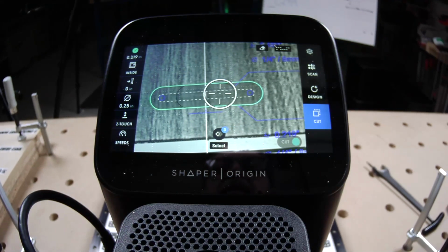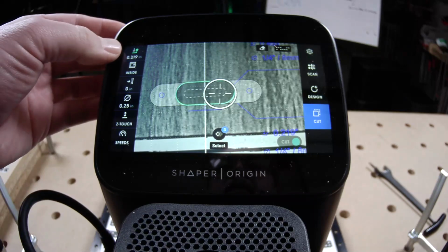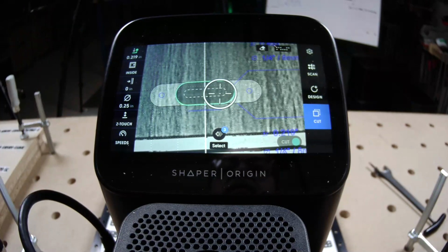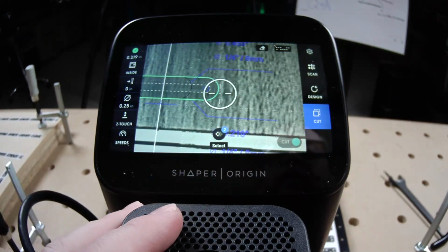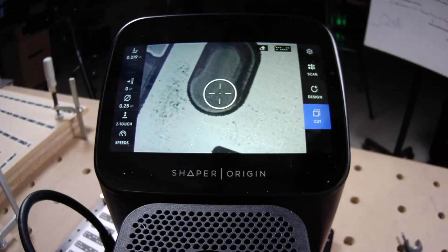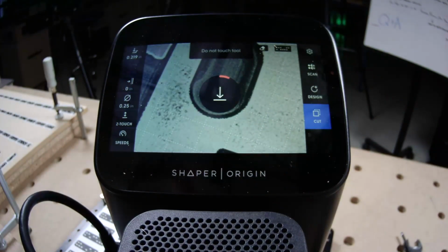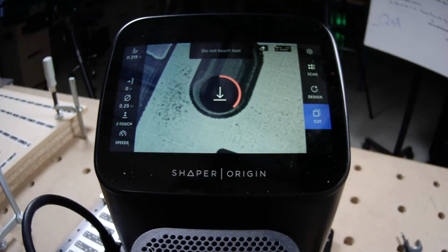And if I come to that center part, because sauce hinges have that double-stepped depth pattern, I know that I have some work to do here still. Okay, so let's go ahead and rip this out. Let's cut it real quick. But you should always Z-touch off of the plate. You should always Z-touch. Yeah, that's right. Always Z-touch off of the workpiece.